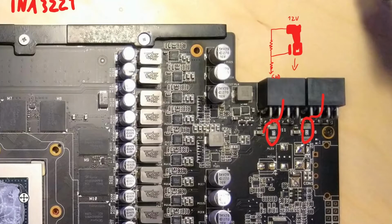So you can just dial in a reading that you want with the voltage divider, and the INA3221 will be completely fooled into thinking we are pulling exactly that amount of power every time we do anything. Like, we are constantly pulling, let's say, 5% of TDP, no matter if we're idle or running a benchmark. And that's how you can completely get rid of the power limit. It's just completely gone after that. Sadly, there is an issue.